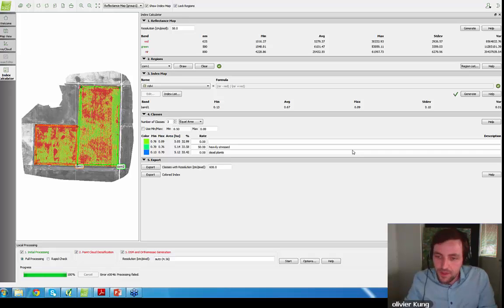Okay, a question about stitching. What is the minimum amount of pixel damage I can have? I'm afraid that stitching artifacts could affect maybe 10% of an image slice of a research plot, if the plot has several stitching seams running over it. With the reflectance map, we do not do seams. We do not do traditional stitching in the sense that we use one image and another image and put a seam between them. In the reflectance map, every resulting pixel is computed by integrating as many cameras as possible, as I said before, taking into account the angle of incidence and also where it is in the image. By doing that, we avoid having strong seams.